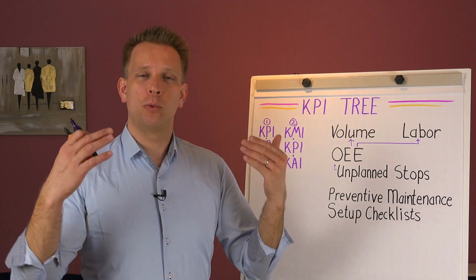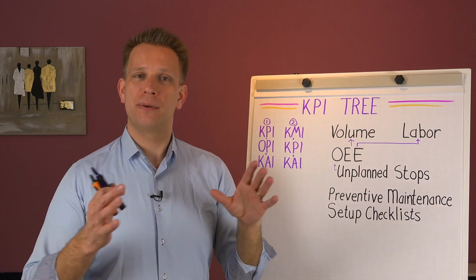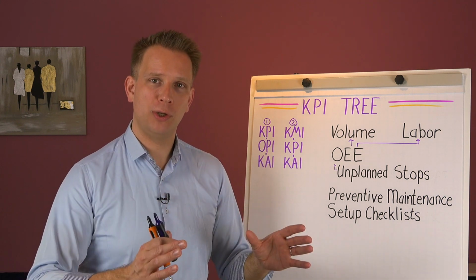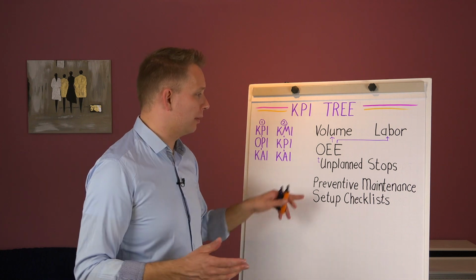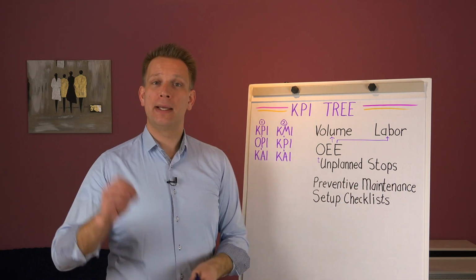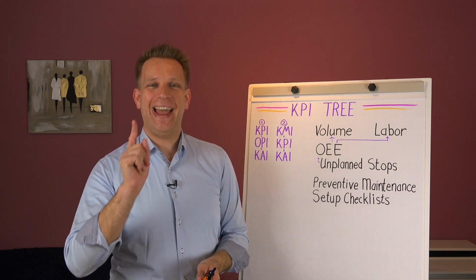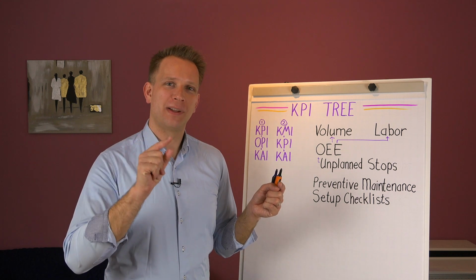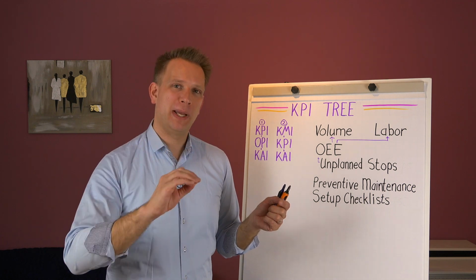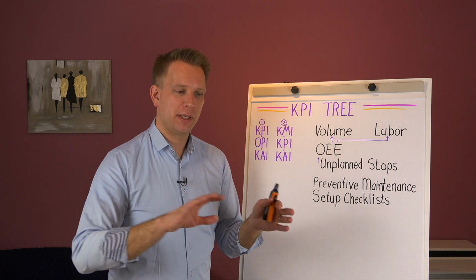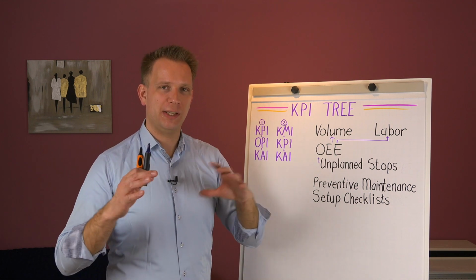We've got the stuff there, we've got trained people doing the inspections, but we're doing our preventive maintenance tasks, and we're doing that on time and taking correct action for it. And one of the more common indicators that you use for that is the on-time completion of preventive maintenance and inspection tasks, and the on-time completion of not breakdown but repair tasks within the maintenance system. See, and here we get into maybe some detail on how we generally see those maintenance tasks.